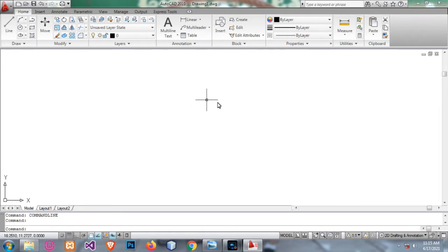The drawing limits will be the workspace that we selected to work in and can be specified using 2 points. The first one is the lower left hand corner and the second one is the upper right hand corner, so it is in a diagonal direction.